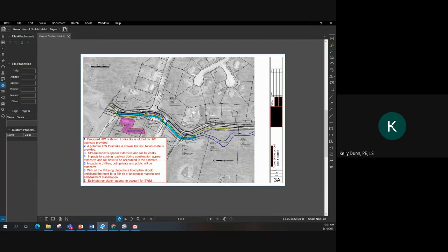From a floodplain standpoint, placement of fill in a floodplain can be a showstopper, and the studies to prove that its impacts are okay are costly. The applicant does have a $120,000 PE hydraulic estimate, but due to the level of impact shown, the need for studies, stream relocation designs, stormwater system designs, including stormwater management, nutrient credit purchases, etc., I would suggest taking a look at this estimate a little bit closer also.